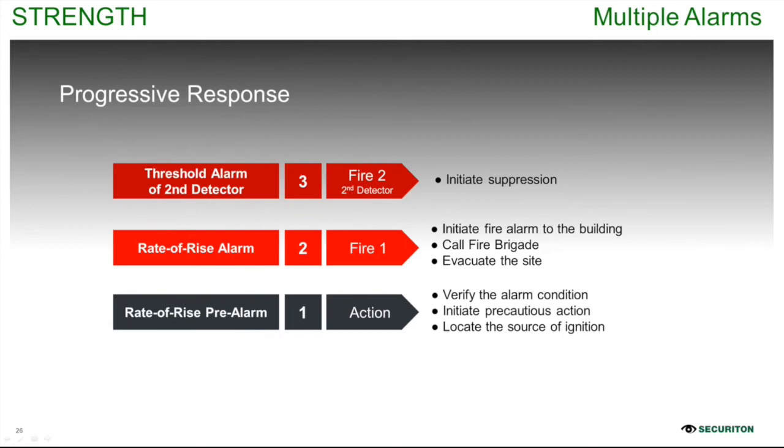Compared to the competitors or the other types of probes or fixed temperature detectors, they may not have such facilities available to cater for different stages of alarm levels, and the earliest action possible may not be possible. Okay, that puts us at risk. They only work when the fire happens, and sometimes the fire can happen in a very fast manner, because we are talking about temperature ranges from 120 degrees and above, a very harsh situation where fire can happen in a very drastic manner.